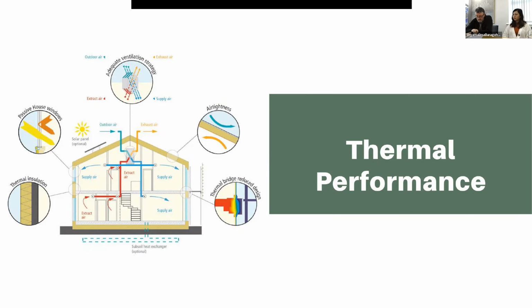The building mass is also very important, and Shawalima touched on that, and a couple of the materials she spoke about, the rammed earth walls and the sandbag walls. They have density and mass to them, and in the daytime they can absorb heat, which they can slowly give out to the building. In the night times when it's cooler, they can cool down and give that heat back into the building in the daytime. So it's a very natural way of regulating the temperature of the building.